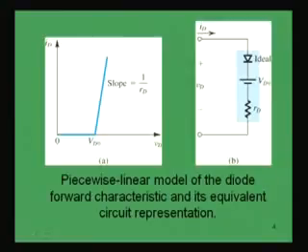This ideal diode symbol is to show the current conduction path, and as this barrier potential or threshold voltage is opposing the conduction of current in this direction, this opposition is shown by this battery, which is VD0, that is this barrier potential or threshold voltage or cut-in voltage. The same name denotes this cut-in voltage only, different names are used for this voltage, and this is the average resistance.